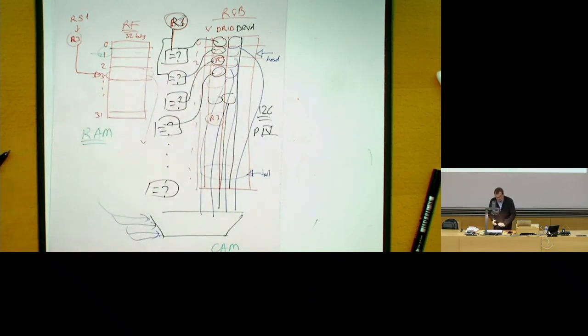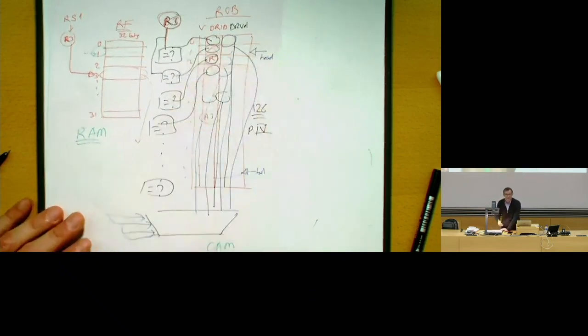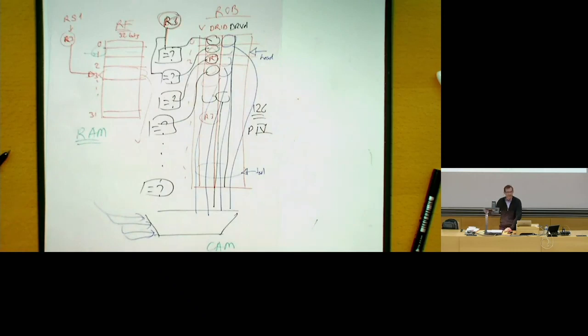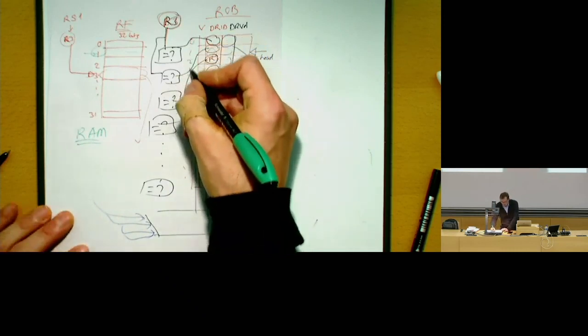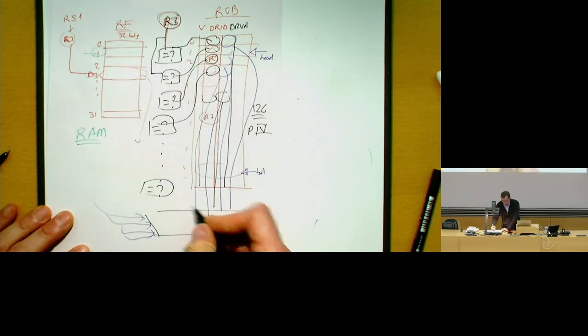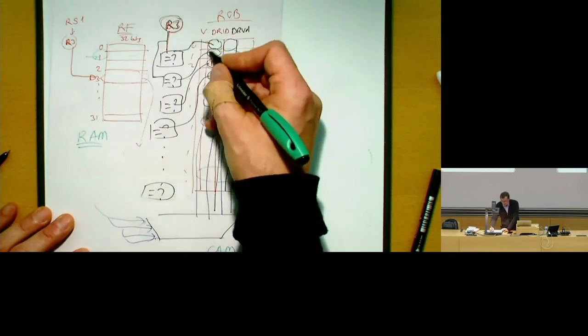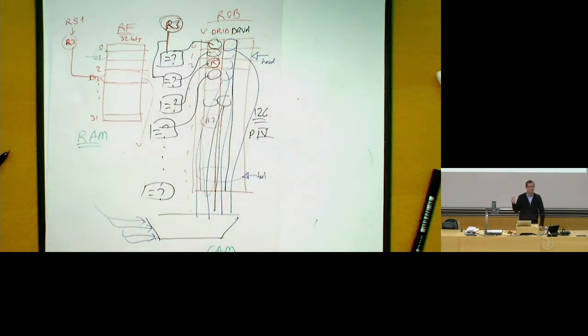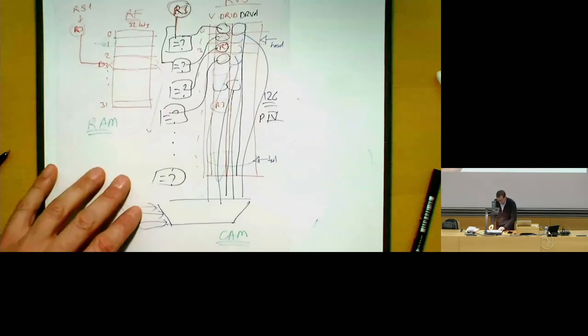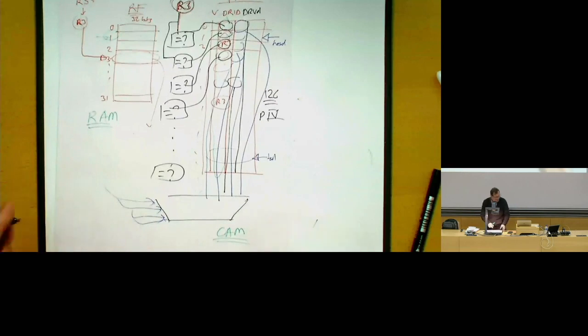It's easy to access. Here you're looking for something that's inside the content, that has nothing to do with the address. The address is all these 0, 1, 2, 3, up to 125. But the content you're looking for is R3, which is really stored inside the content data. So you need to build this sort of structure to get the content, to match the content. Okay, so that's a reorder buffer access for you.